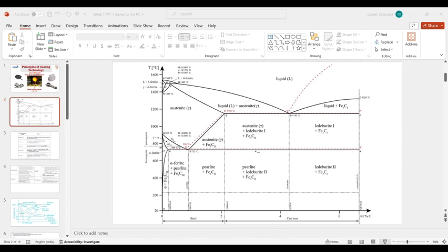And dendritic segregation associated with inhomogeneity, whatever dendrites have formed in the system during the casting and solidification process, occurs because of thermal and constitutional supercooling. Yes, that occurs during your solidification process due to thermal and constitutional supercooling. If we provide supercooling and chills during our cooling process, then dendrite formation will be there. So answer is both first and second.